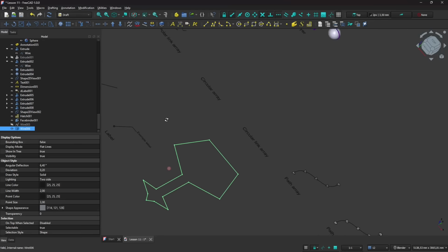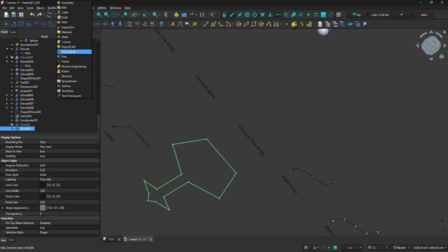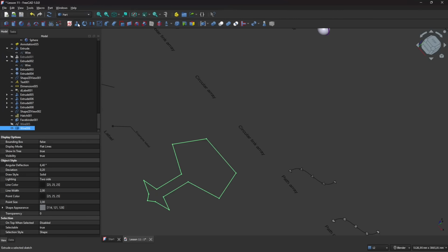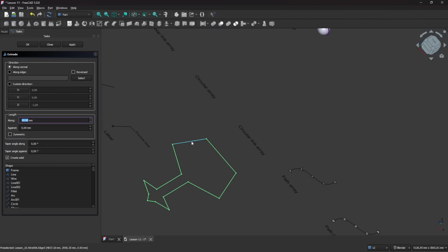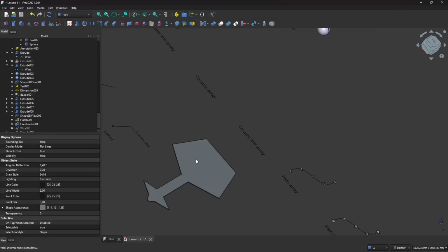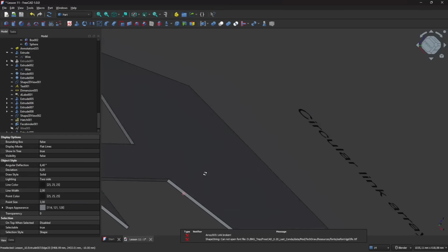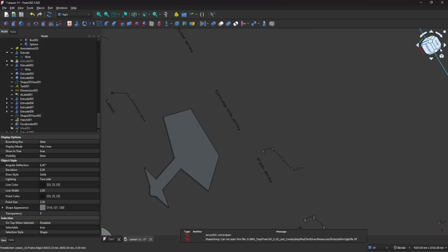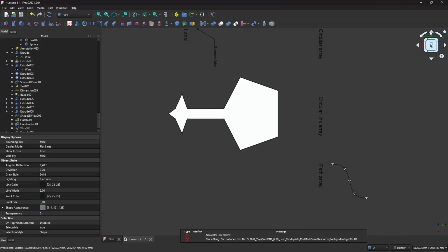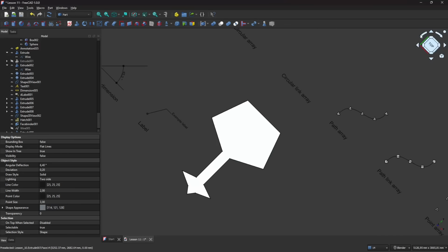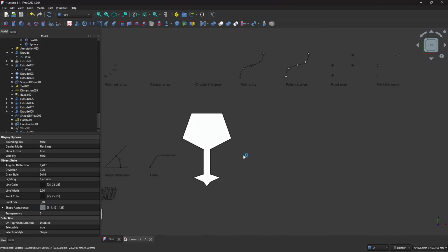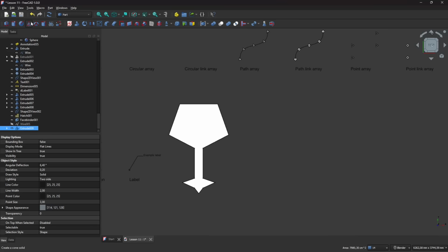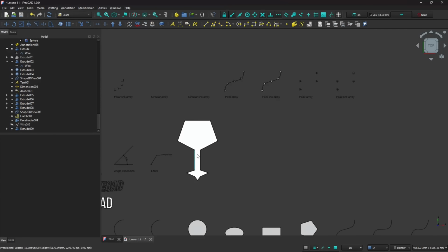and this is ready to be used in 3D. So if I go now in the part workbench and I click on the extrude and I type any number, you can see that this is going to be now a 3D object. So again, the close relation between the 2D and the 3D. Now, this is just to explain the mirror. Let's move on, and I'm going to go back to draft.